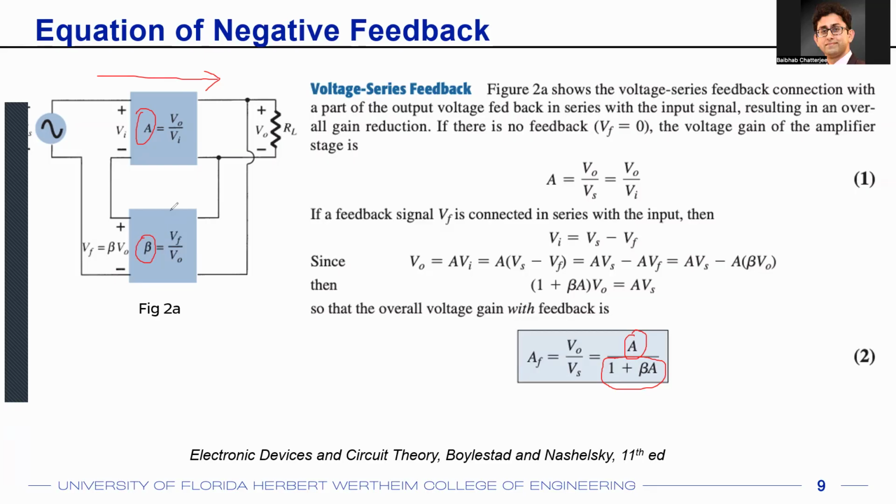If you create those resistances or buy those resistors from the same batch, manufactured by, let's say, one of the resistor manufacturers, even if 1 kilo ohm becomes 1.1 kilo ohm, and 1 mega ohm becomes 1.1 mega ohm, generally they go in the same direction if they're manufactured in the same batch. So the ratio of those two resistors will remain the constant that you'd like to have. So 1 mega ohm versus 1 kilo ohm is the same as 1.1 mega ohm divided by 1.1 kilo ohms. That is the reason why stabilizing the beta network is usually easier.